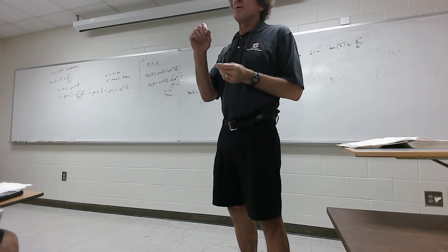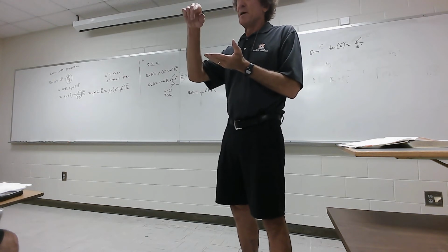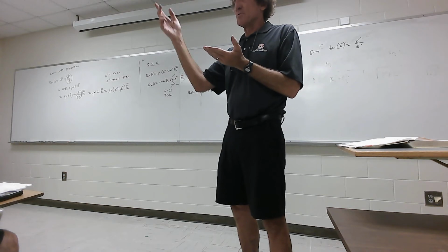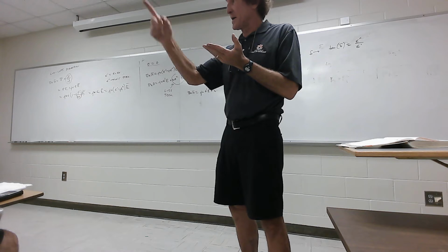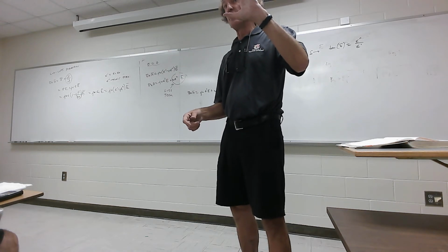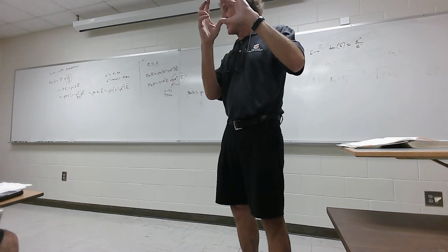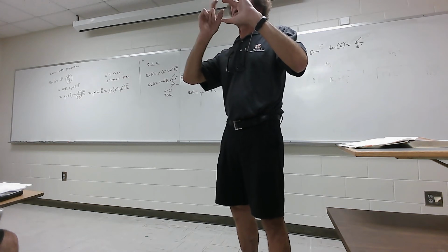Here's the deal. You can have a DC voltage across them with a ripple, but you can never have an AC voltage. You can't drive current the opposite direction through one. In other words, you can't get any kind of full wave effect on those things. The reason is, their dielectrics are like a gooey liquid or a paste, if you ever cut one open, and they flip and they heat up a lot.